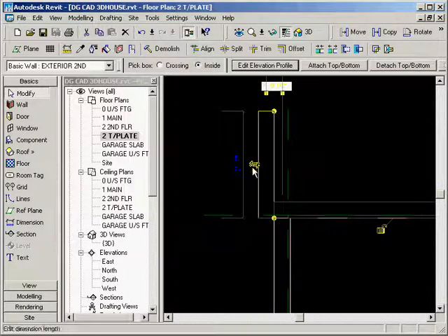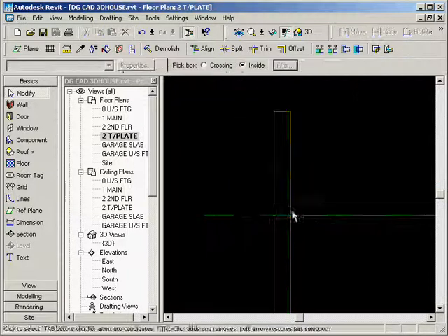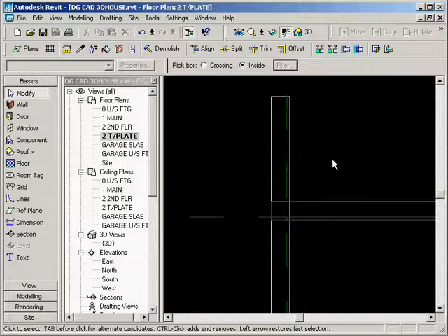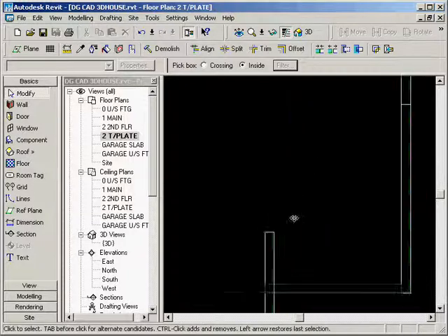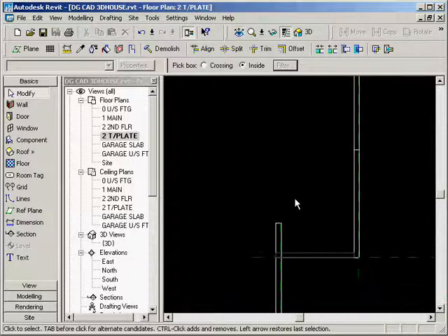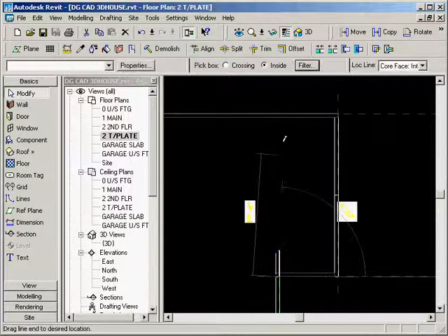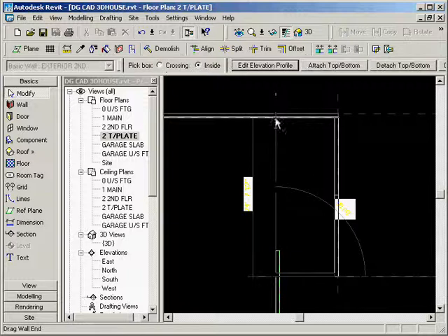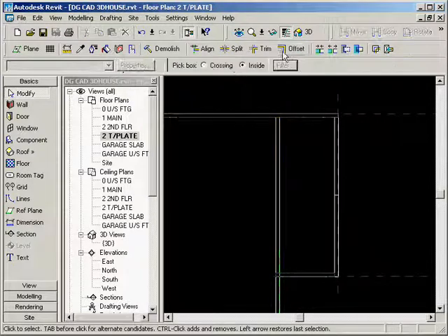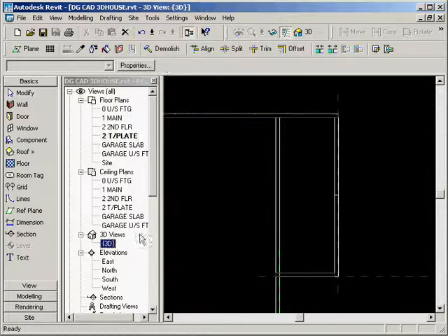We're going to see. So I see that wall there needs to be flipped over to there. That looks a little bit better. There's my stuff. So now I'm just going to extend that piece of wall, which is sitting really high. And I'm just going to extend it over by gripping it and dragging that straight up over to there.